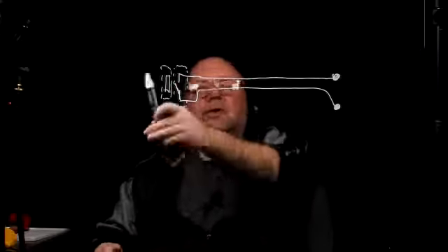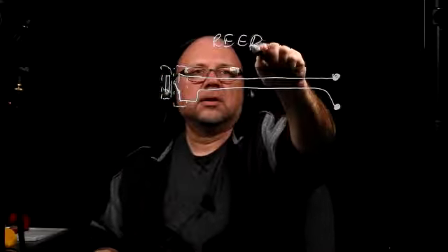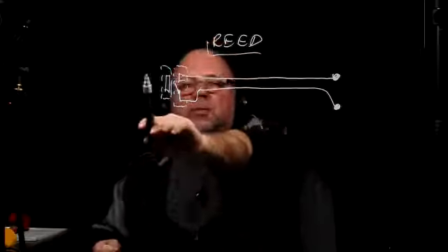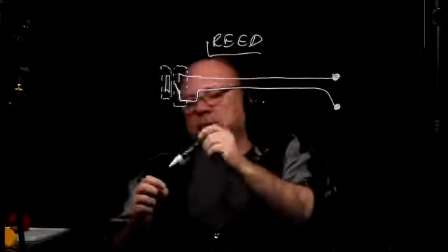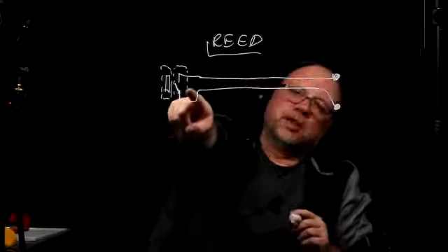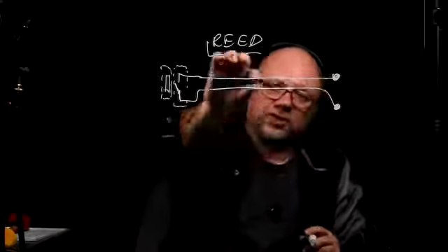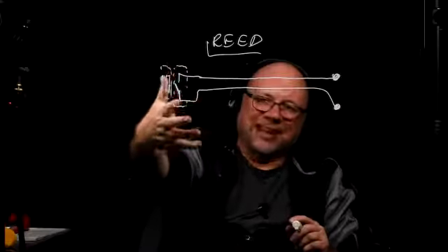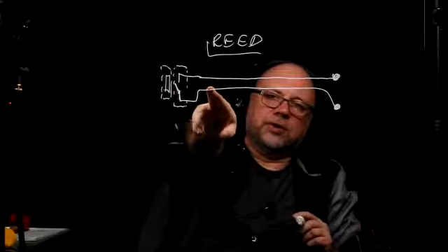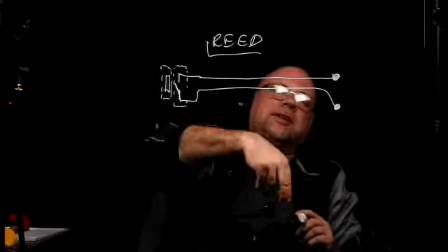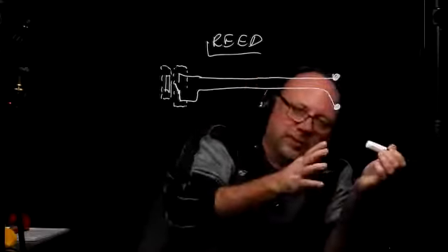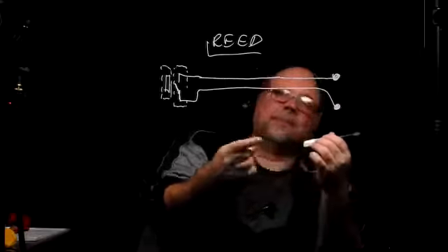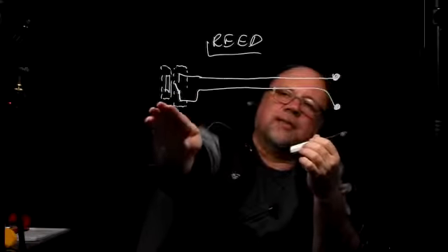Now, when you open the door, the reed type of switch is going to open. When the magnet is in close proximity, it's going to close that switch. All right. Now, in this case, we want the pair to be untwisted, just as straight as possible. The reason is that, remember when I told you that the twist acts as an inductor, and inductors hate change, they oppose change. They are going to give you the change, but not as fast as you would like them to. So what happens if you open and close the door very fast?